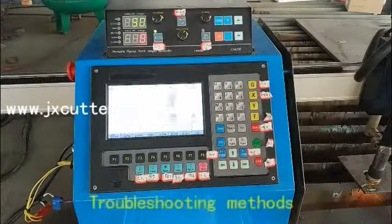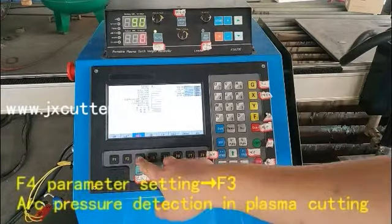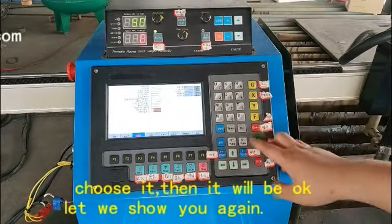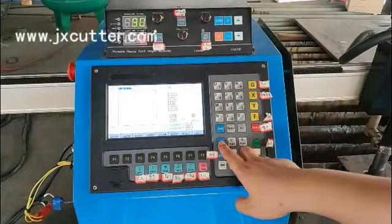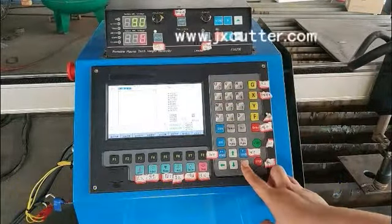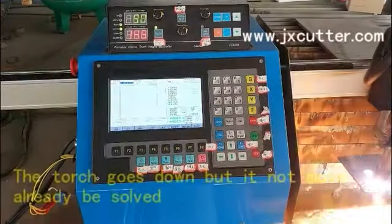Troubleshooting methods. F4 parameter setting. F3 arc pressure detection: in plasma cutting, choose it, then it will be OK. Let us show you again. The torch goes down and it does not move and does not locate successfully. Let us show you again, start. The problem where the torch goes down but does not move has been solved.